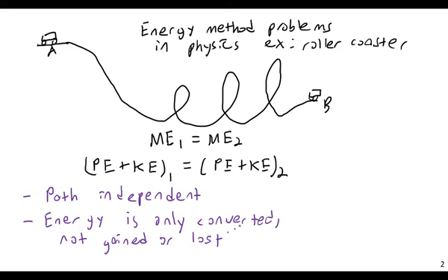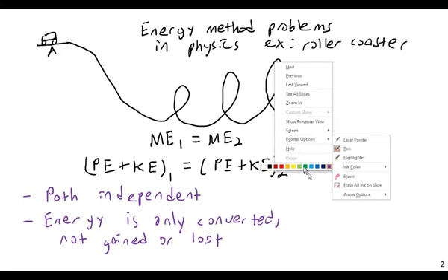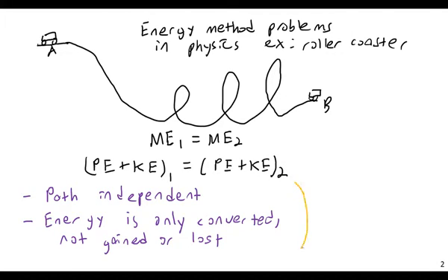And the reason I'm mentioning this is not that it's important to review elementary physics, but it's important to keep in mind that Bernoulli is like this type of problem. Bernoulli is very much analogous to this type of problem. Now, we will later see that we can add terms to the Bernoulli equation, taking into account things like pipe losses and pipe friction and that kind of thing. But the pure Bernoulli equation that we have worked with before, without any kind of losses or turbines or pumps, is equivalent to this type of system. They are one and the same. So again, the very same assumptions are applying.